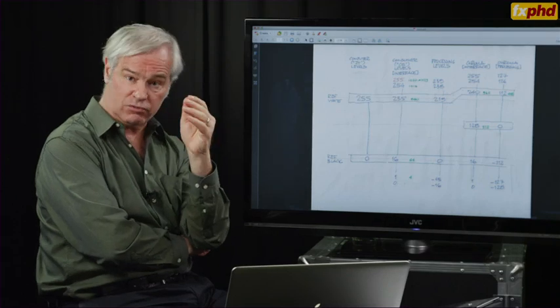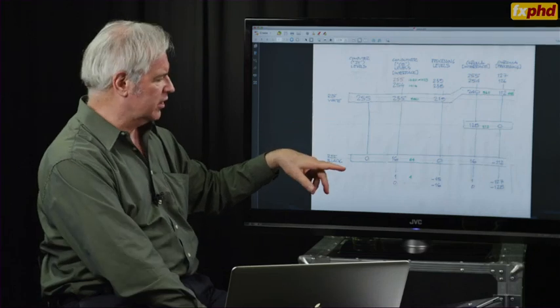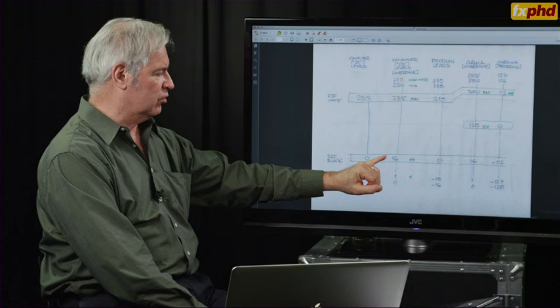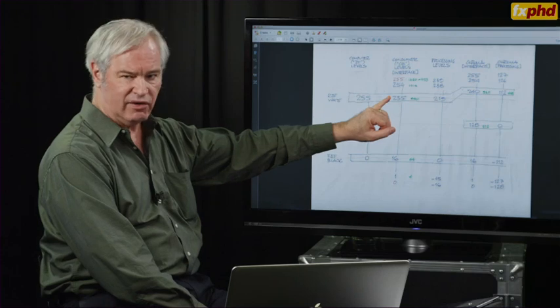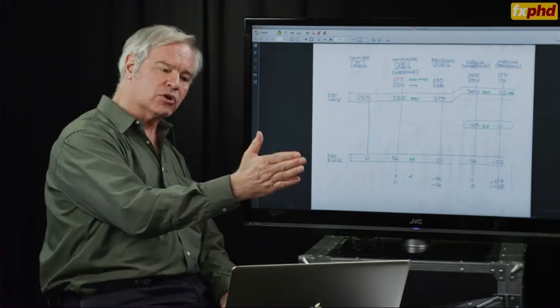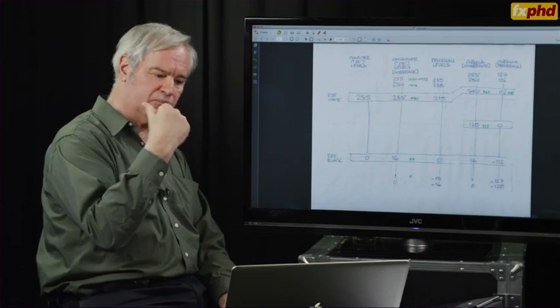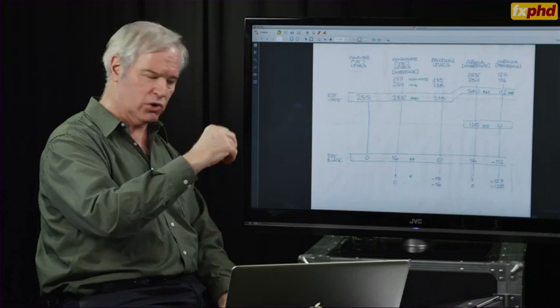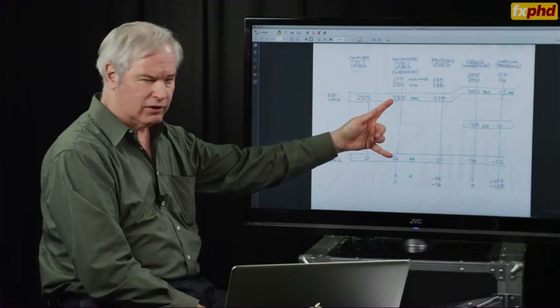And those regions were standardized. Now, they were standardized in 8-bit space in the early days, so reference black was placed at 16 and reference white was placed at 235. And in the consumer domain, 8-bit digital video is commonplace: MPEG, H.264, DVD, Blu-ray, and so on. So these are the numbers that are applicable.